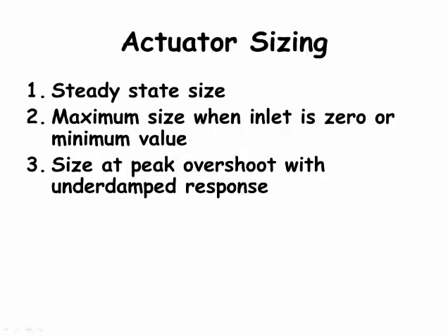Another way to size an actuator would be to base a steady-state analysis when the inputs were at their minimum. You were asked to do this for problem set 6, problem 2, when you were asked to find the flow rate of the concentrated material added to the second mixing tank when the inlet concentration of the material was set to 0. For the fluid heating problem, we could size the heat input and relay based on the coldest inlet water temperature and the highest expected set point temperature.